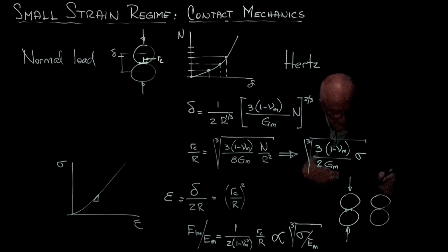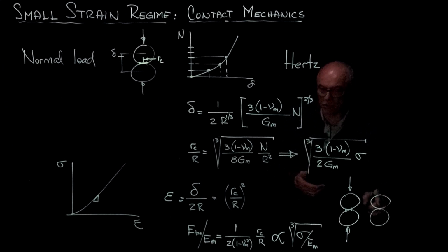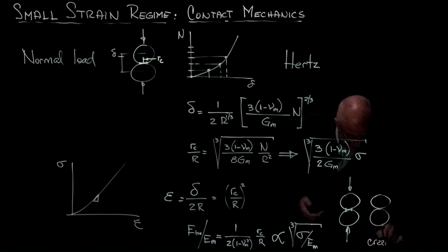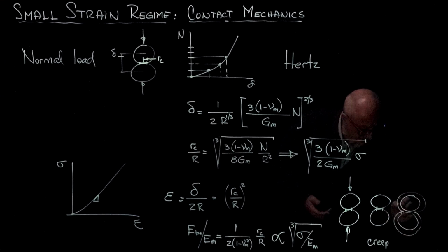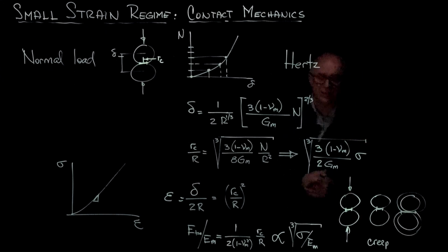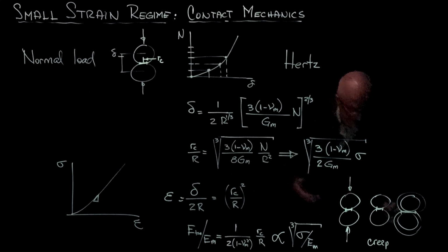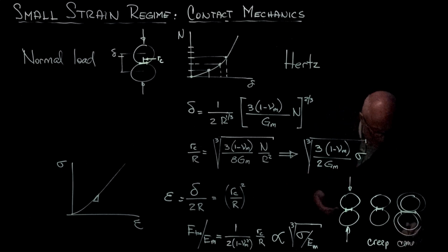Imagine that this is granular salt or lead shot or any real material with diagenesis. Creep will increase the contact size. But there is one more possibility, and that is that the particles get coated with a cementing agent, and now the contact is much larger. And so cementation has a huge effect on the small strain stiffness. So this is cement.